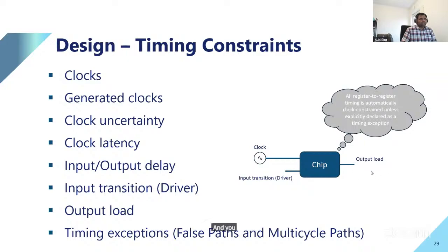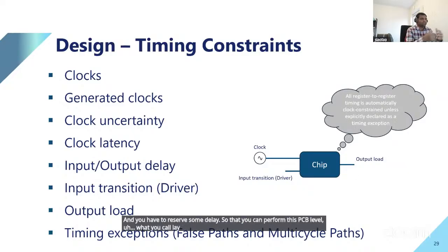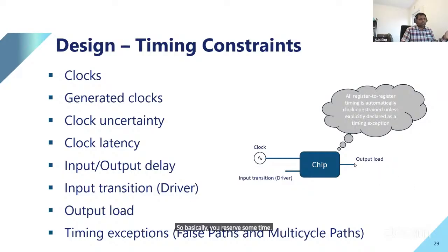And you have to reserve some data delay so that you can perform this PCB level, what you call layouts, and also this off-chip device has some requirements. It also needs some time to settle. So basically you reserve some time as output delay.